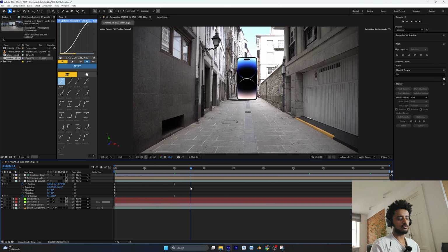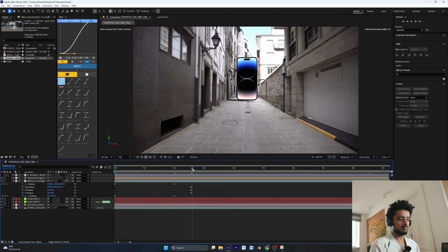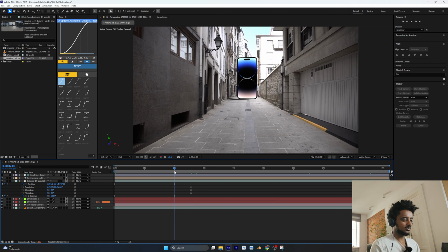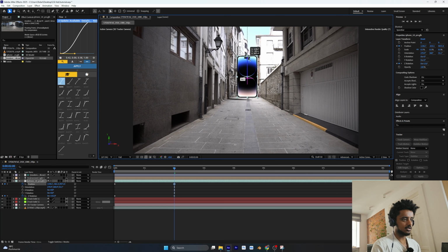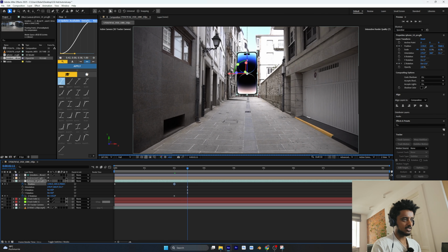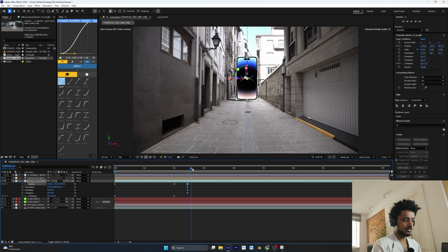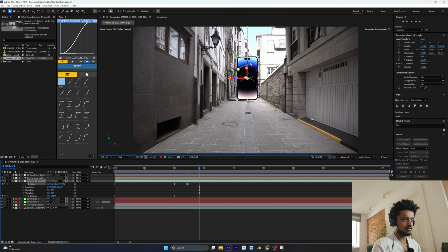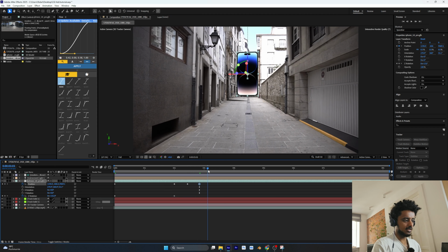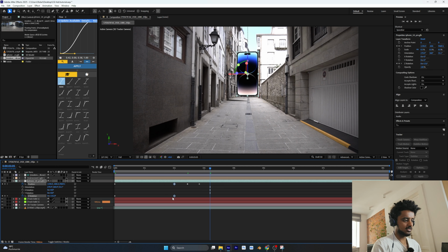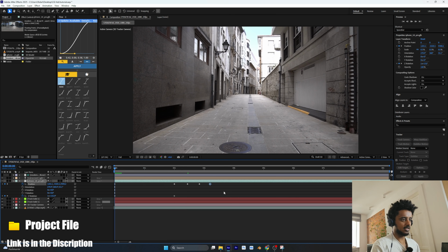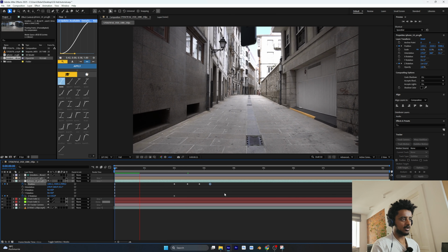But I wanted to also give it a little bit bouncy motion. The way I'm going to do it is around the 2-second mark, I'm going to drag it a little bit up like this and go a few frames and drag it down, and another few frames and drag it up. And then at the end, I want this position keyframe. So I'll just copy and paste it here. So let's check back at it. So it's revolving around, coming back.